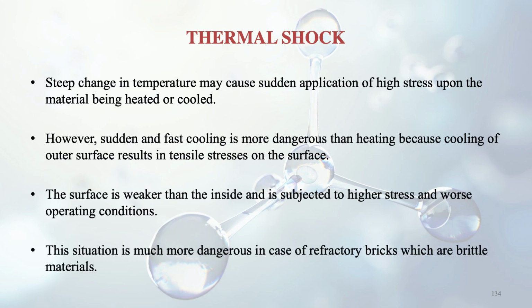And this situation becomes more dangerous in the case of refractory bricks, which are brittle materials. So if the surface damage is taking place earlier, refractory bricks are brittle and they can get damaged from the top. So when we talk about thermal shock, we also need to know about the resistance to thermal shock, because only then can we gauge how good our material is at preventing cracks and damage.